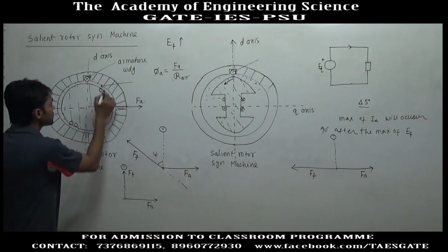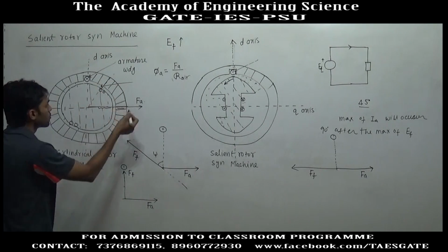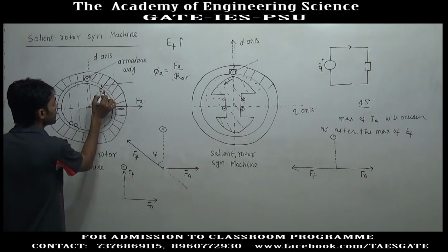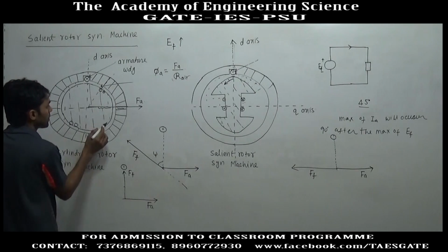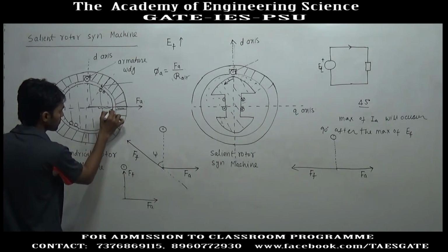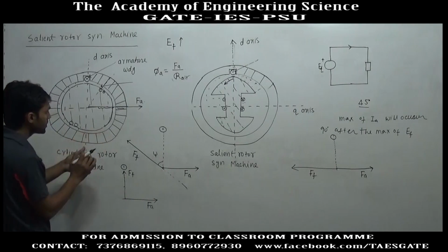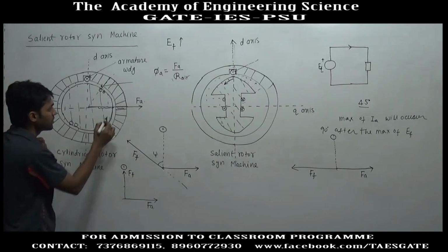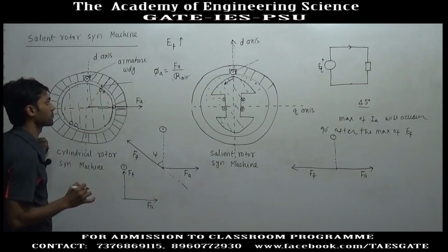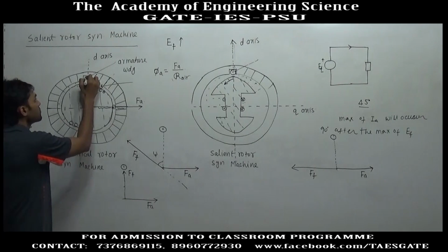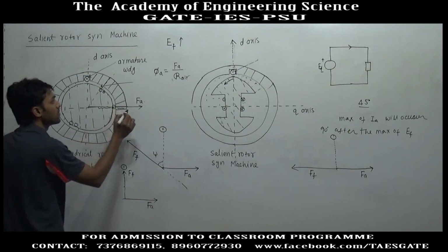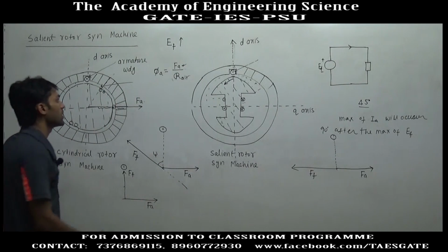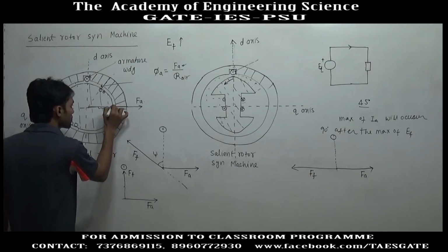Now, instead of this angle psi, if the rotor was rotated by some other angle, let us say 90 degrees, these two conductors would be here and this part of the rotor would be here. So, if the rotor has rotated by any angle, the air gap MMF would be the same, and the maximum armature current in this conductor will have a definite value of maximum armature MMF, and the air gap is always fixed.